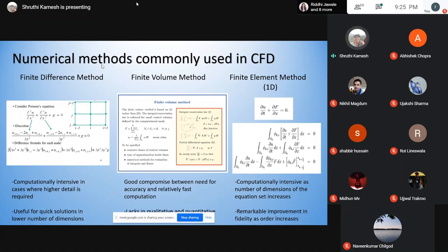I'm saying that I hold a certain set of constraints, but I also relax them a little bit using that particular weighting function. So in finite element, you solve for your field variable, which is your u, as well as your weighting function, which is your phi, given over there, phi ki.